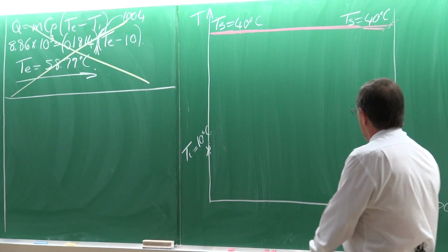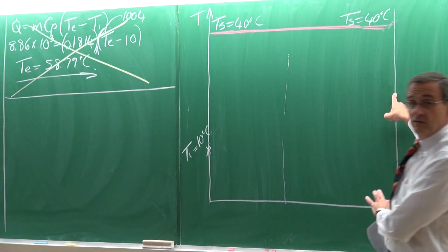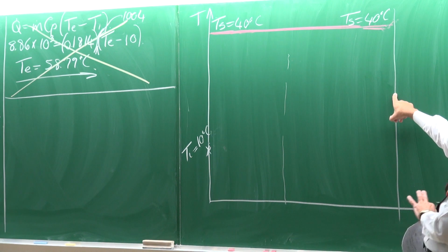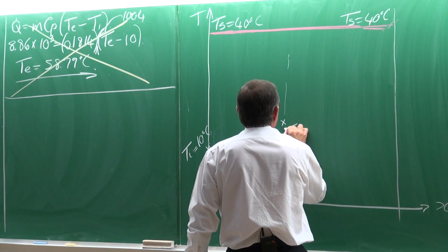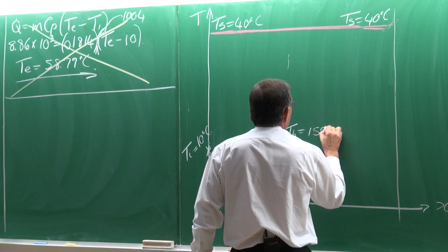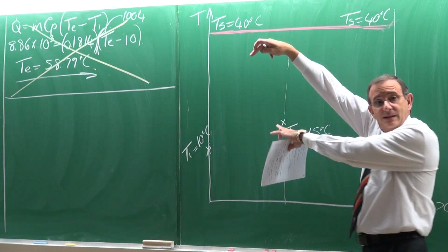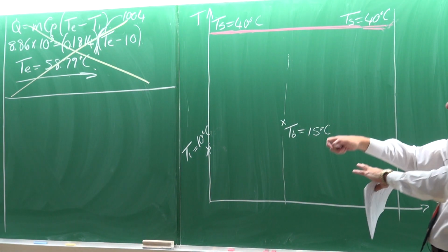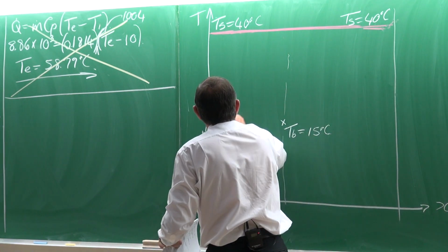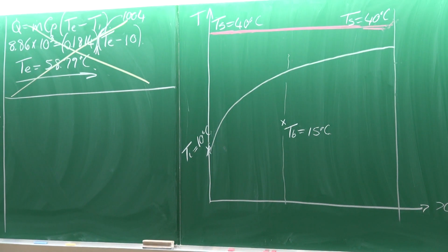And my selection of the bulk temperature, I don't even know what this outlet temperature is, was 15. So there's the bulk temperature of 15. So I cannot use this delta T to calculate the heat transfer rate. I need the correct temperature difference, because with a constant wall temperature, you're going to get something like that.